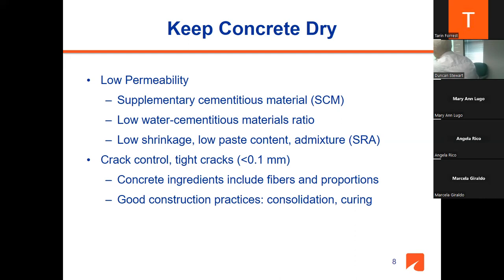We know that if we get tight cracks, meaning less than 0.1 millimeter. To give you an idea what 0.1 millimeter is, it is the thickness of a hair. It's a very small dimension. And we know, for example, in VDOT that we can fill cracks that are larger than 0.2 millimeter. So now I'm talking about cracks that are so narrow, and we are able to do that. Okay, so if we keep those cracks so tight, things cannot penetrate into them.